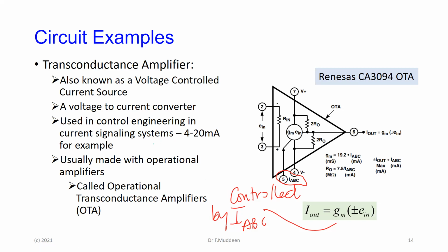If you think about it, a typical control plant is something that is spread over a fairly large area. When things happen in one part of the area, there has to be a way of communicating what is going on in that area to another part of the plant, or to the control unit or the control room and so on. One way of sending the signals is using something called a current loop.